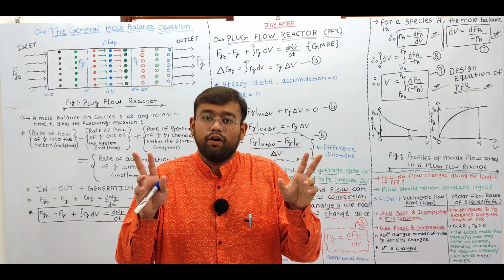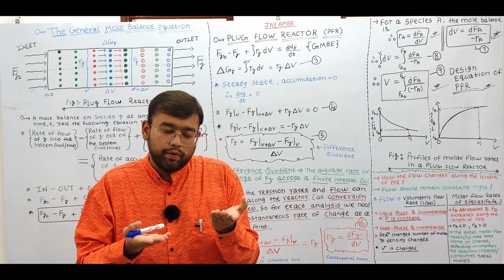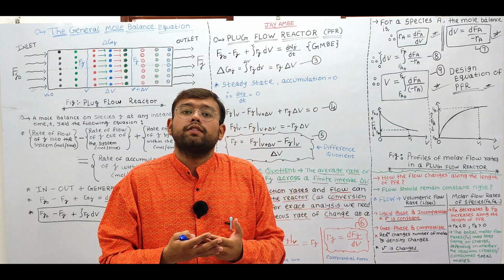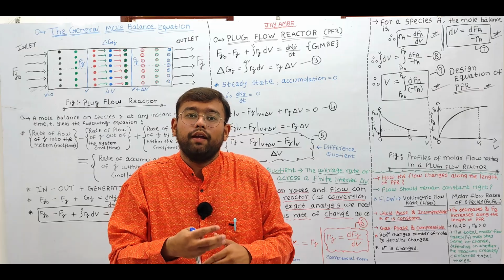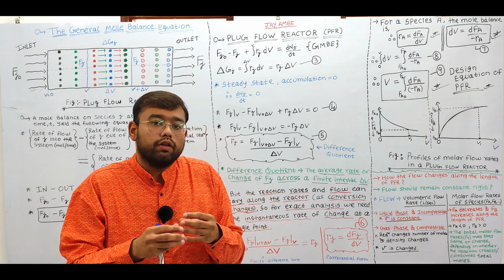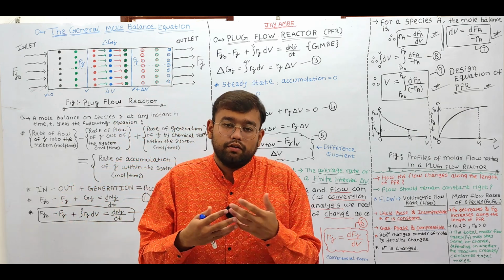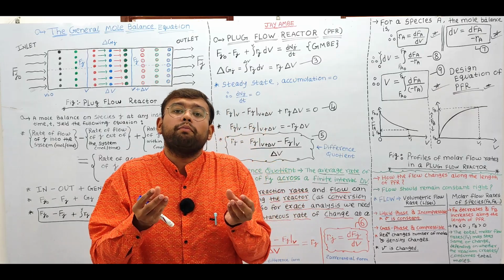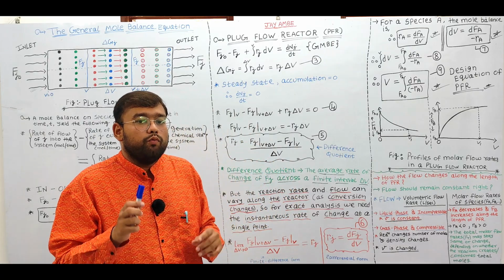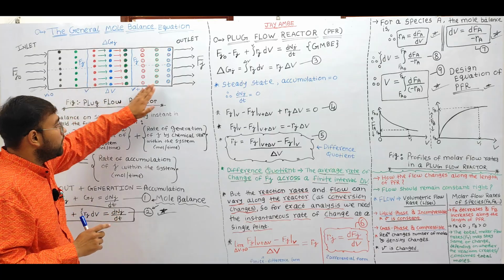The term compressible means all gases can be compressed, and the density of the gas will change by applying a significant amount of pressure and temperature. During the progress of the reaction and time, the density changes, so these are called compressible fluids. Due to this, the volumetric flow rate will not remain constant throughout the length and volume of the reactor.